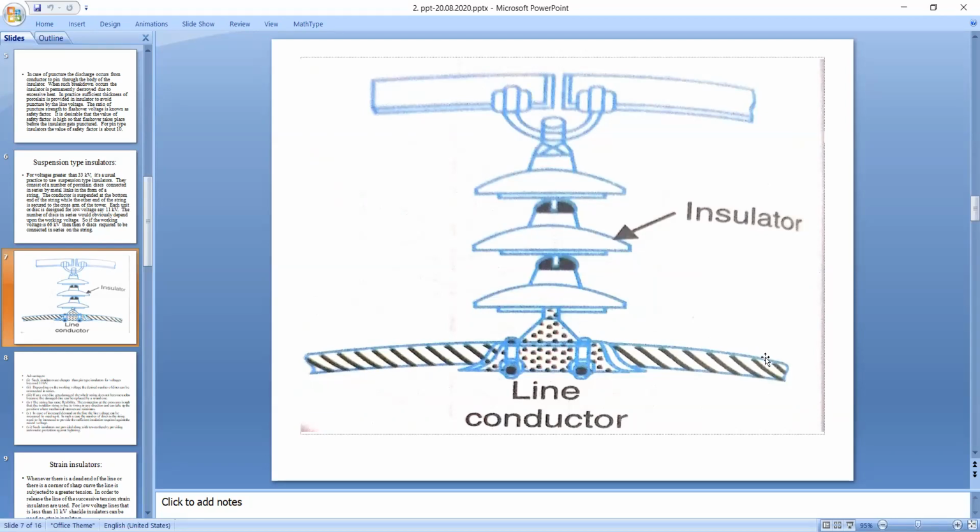Okay. So say system voltage or line voltage applied is 33 kV here. You have the line conductor and the system voltage is 33 kV. So 33 kV is applied on the line conductor. So that means if you are applying here insulator string, what should be the voltage rating of the insulator string? That should be also 33 kV, so that it can tackle the dielectric stress of the 33 kV voltage applied on the conductor. Then only conductor will be protected against electric stress or dielectric stress.